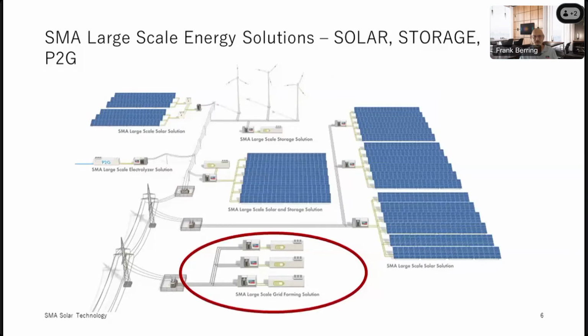And as Julia mentioned, when we talk about grid forming converters here at SMA, we're specifically talking about battery energy storage systems. Not because it's the only place you can technically deploy grid forming, but it is where the technology is, say, the most mature, and it's the application where the DC source lends itself to grid forming applications, I'll say best, because of the predictability of the power and energy in the battery. You always know what's behind the inverter. So in that context, we'll be talking about grid forming today.